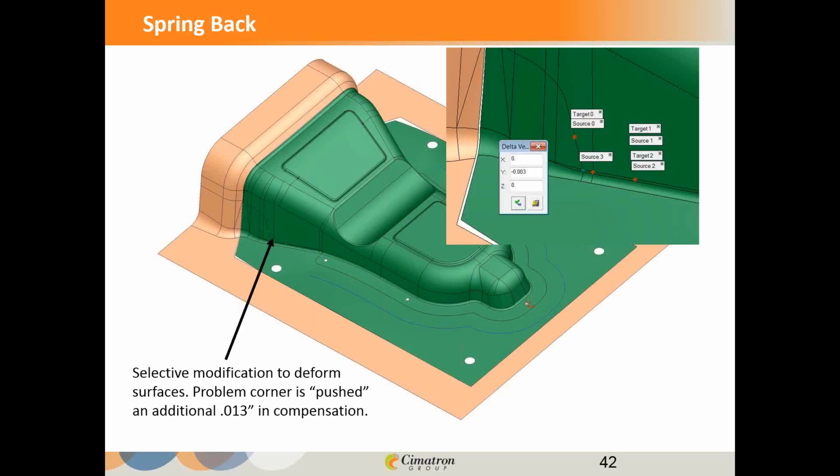But right about where that particular point is, right here, source 3, that would be the point where I'd push it in 13. I would also work my way up and down along that edge so that I can control how much it's moving. So it doesn't drastically go from 0 to 13 and give me any sort of squiggle, but I'm controlling it, smoothly changing those values. That's why I put in a lot more control points. You see 3 more control points in red. Real practice is I would probably put in more so that I can get that nice smooth edge like I like. Okay.